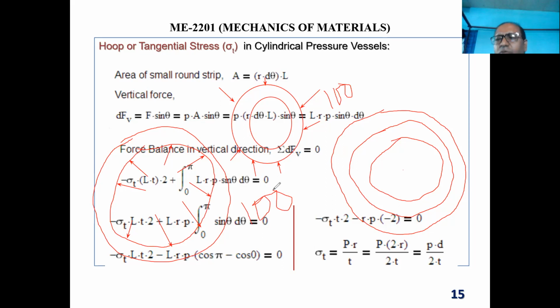Now, how do we figure out the contact pressure? It depends on interference. We keep interference 0.005 inch, right? Then you can put interference 0.01 inch. If you increase the interference, the contact pressure will be more. So right now there is no inside pressure. There is a contact pressure, then you put gas, then there will be inside pressure.